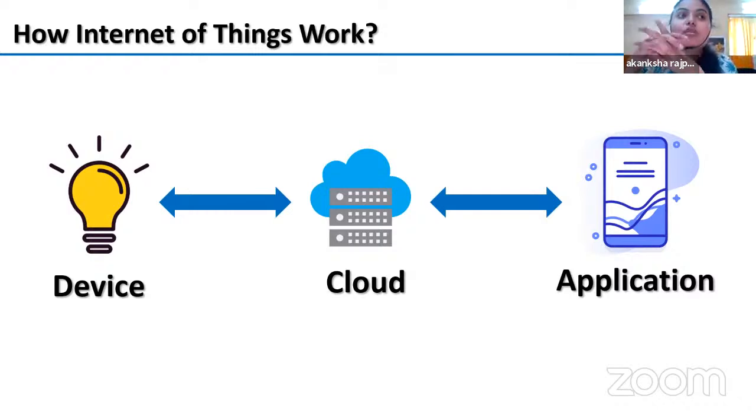So that's where you have to use wireless communication, and in wireless communication you have to use these kinds of antennas. I can simply replace this Arduino with this NodeMCU, because in the Arduino case I have to connect the external ESP module and a lot of wires. So it will be more complex compared to this NodeMCU. If I'm comparing this Arduino with the NodeMCU, in the NodeMCU I have this on-system Wi-Fi module.